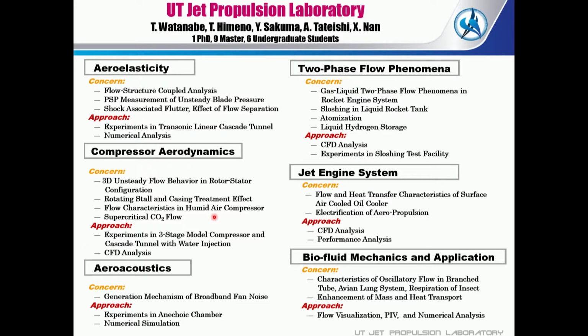We inject the water droplets into the inlet of the compressor. So it's very effective to enhance the output of the electrical generation. But a very big problem is erosion, of course.